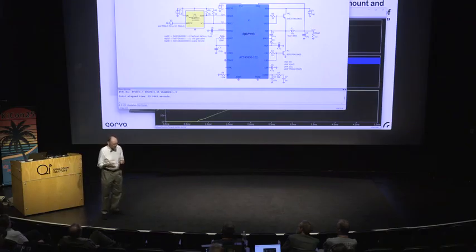Now, what I'm trying to say is, yes, break your big circuit into smaller circuits, and yes, there's a disjoint between the circuit that you use for PC board generation and the one you're simulating. But don't try to simulate a literal version of that smaller circuit. That would be my advice. And if your simulator can do that, you're ahead of the game. It just makes the process less error prone.